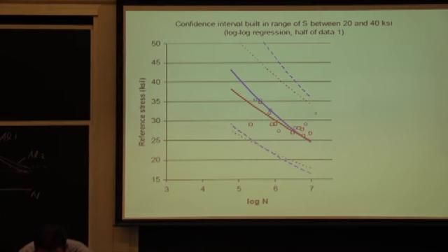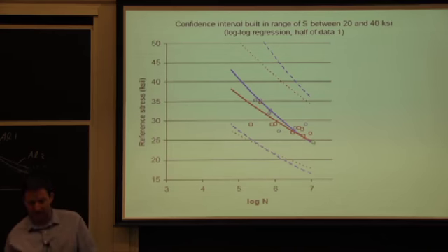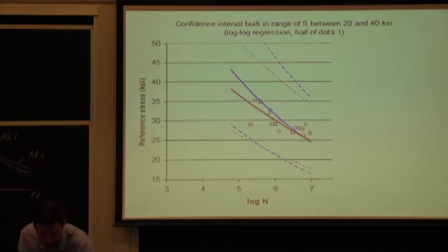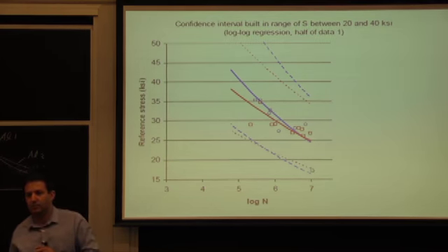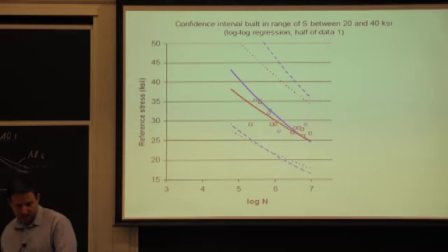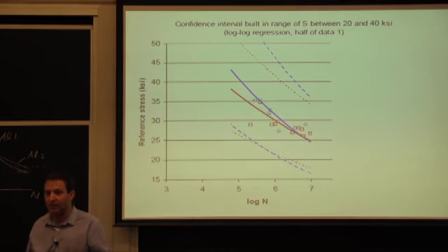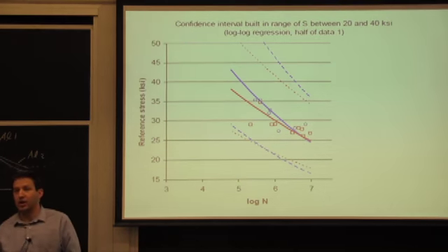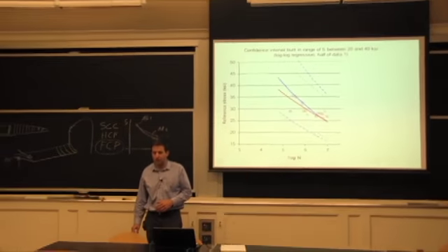If I'm going to come here and say, well, this curve looks really good, maybe 10 to the 7th cycle, 25 KSI, that's what I can take. If you take into account the risk of variation from your measurements, you'll be down to 18. So if you say it's 18 and the other is 17, well, now we have a change. It's different from one to the other.